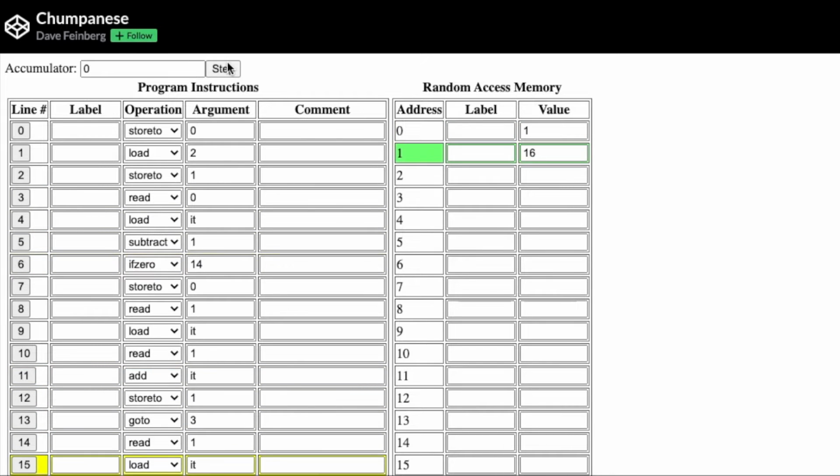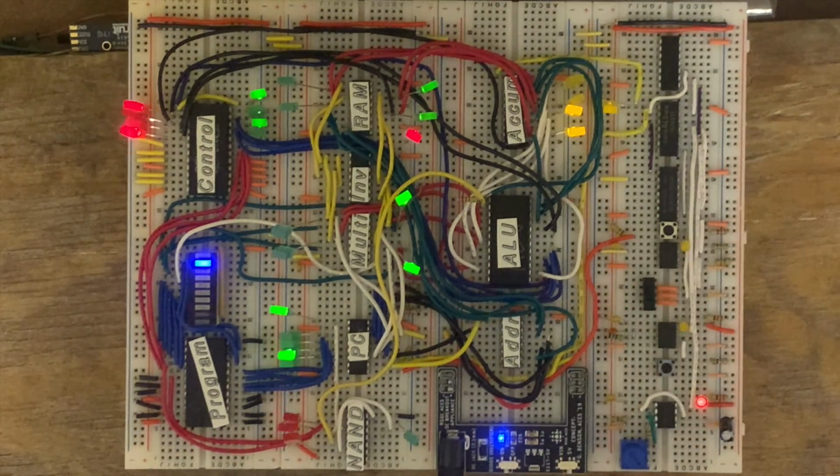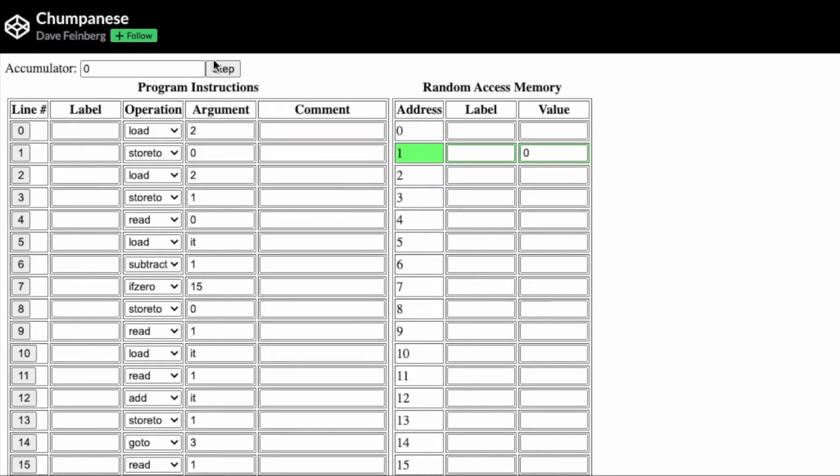Theoretically, something like that could be accomplished within the CHUMP using an external program counter and a few wires, but was not practical as I wanted my build to be completed within 4 breadboards and only came to this conclusion late in my build. So, instead I decided to alter the code, moving the final load function to the beginning, accomplishing my goal but at a cost. That being the absolute value would need to be read through the multiplexer.